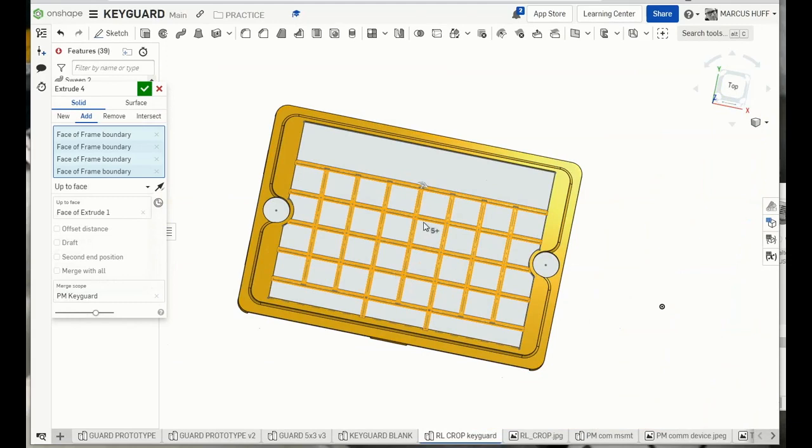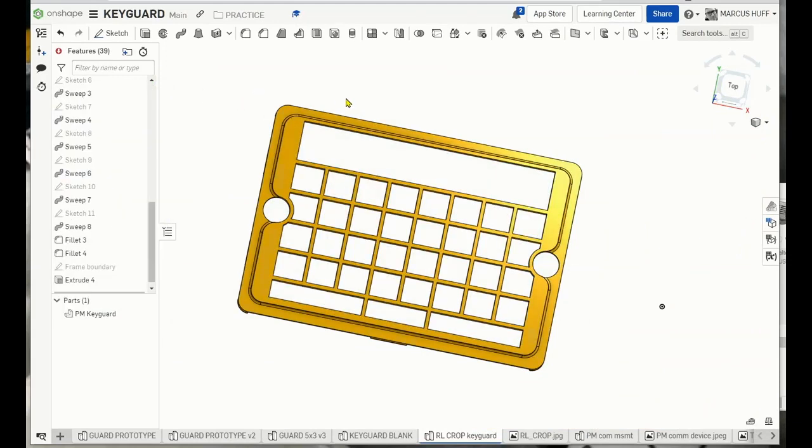All right, in this process, when I was doing the offsets, I copied and pasted the hashtag G line so I could just copy and paste that in as I went. One of the things you need to pay attention to, you may have noticed, is that if you click things that aren't necessarily connected, it may complain and turn the sketch red. Just keep clicking. If you click the wrong thing, just hit Control Z.